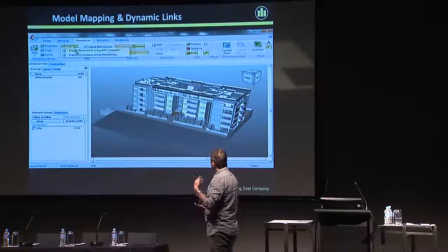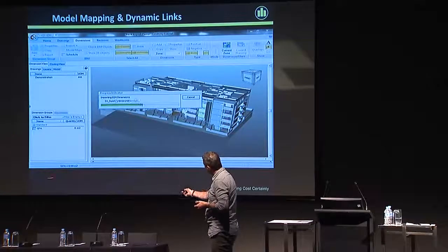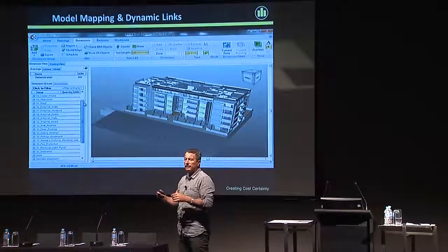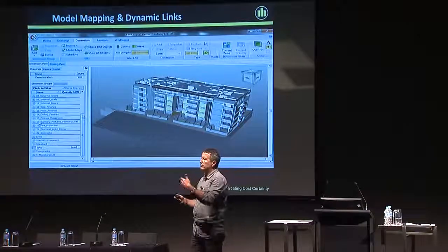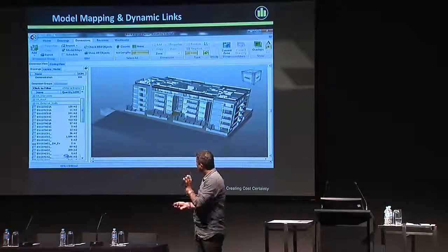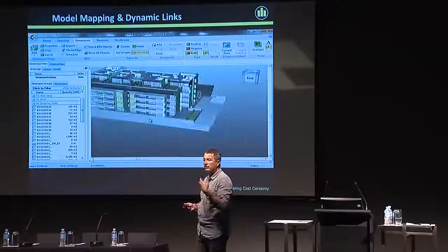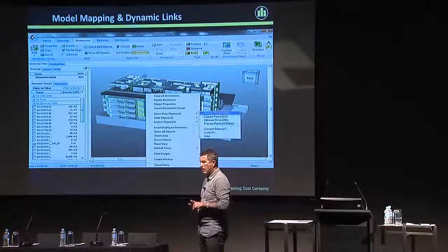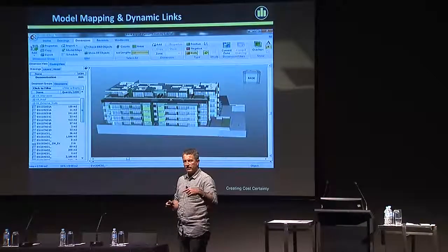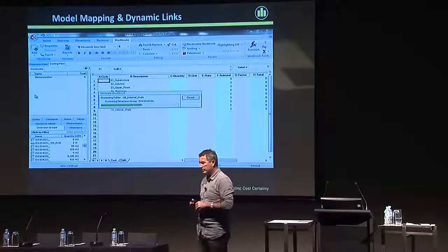The next phase is we start to import the quantities that are within the model itself, and you'll see them propagate in this area here. They are going to come in elements, so something that Qsys has used to be able to look at the actual costs. And they'll propagate through here. We'll be able to find what the area of precast panels is. We can separate those and look at them in their own right. And none of this is driven by coding within the model from the designers, nor is it driven by their families. This is all driven by dynamic links within the software itself.